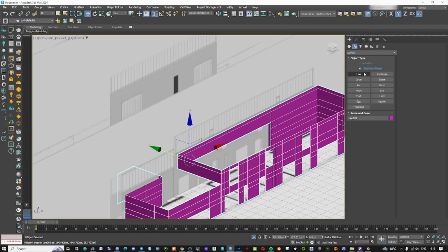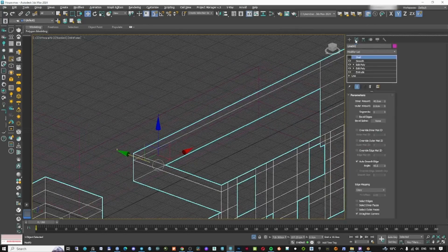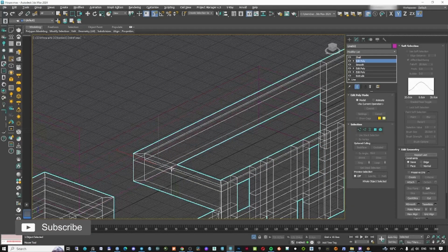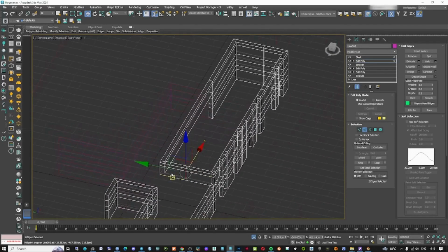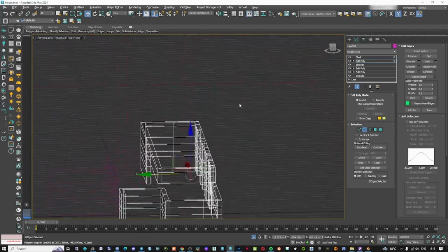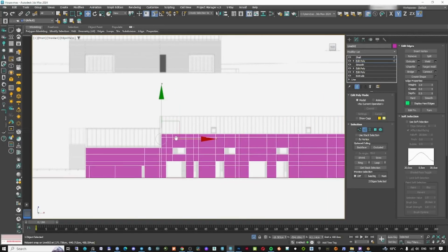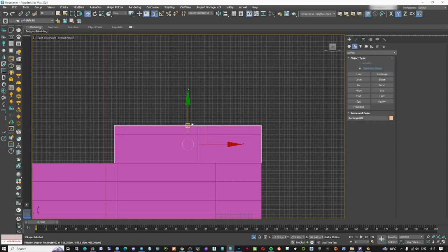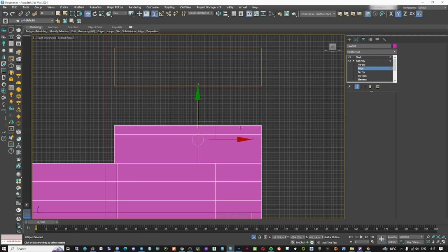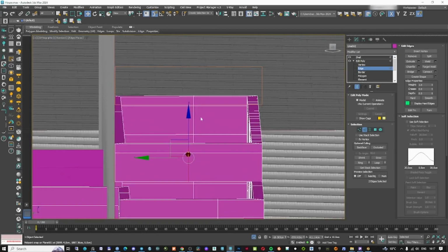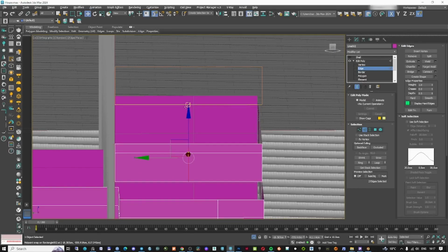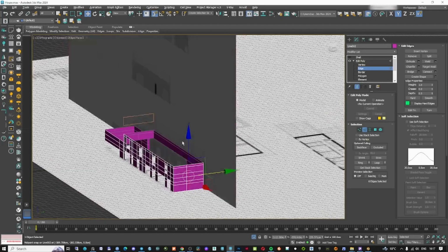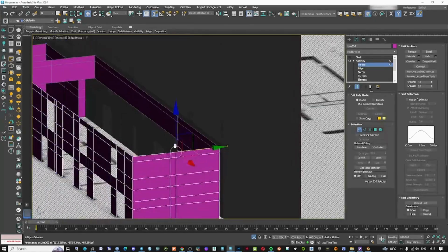Now I'm going to create also some other loops inside this house. So in this way we can create also the attic. I'm creating here just a simple rectangle just to use it as a reference for the middle point, and then afterwards I'm just gonna extend my vertices so I can create the attic.